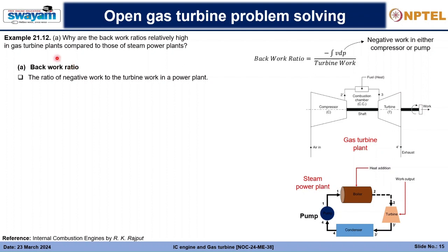So we already know how a gas turbine operates. So that is the compressor section. Air enters the compressor, gets elevated to a particular pressure, then it goes into the combustion chamber. It receives some amount of heat input. It elevates to a temperature like T3 with the highest amount of enthalpy. That enthalpy is utilized in generating the work output from the turbine by expanding the gas, and the rest of the gas is going through the exhaust. So that is of a gas turbine power plant.